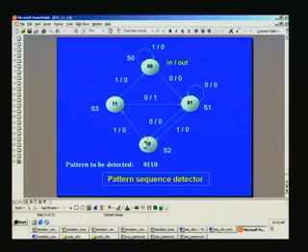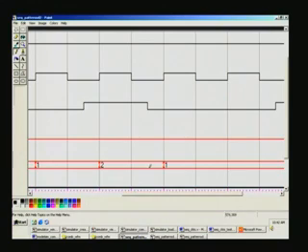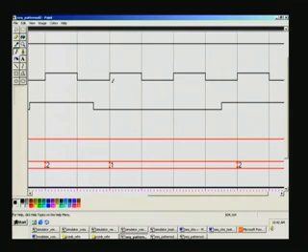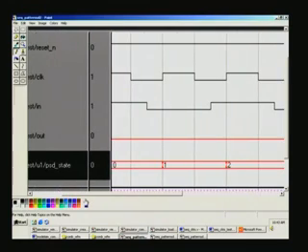In state 2, if input is 1, is it 1? It is 0. 0, okay. If it is 0, then it should go to S1 state. Is it okay? Okay. Right? Input is 0, yes. I think the input is sensed at the positive edge of the clock, yes, as well as the output changes simultaneously, immediately, and not in the following clock pulse. No, the output remains constant 0. We have not encountered 0, 1, 1, 0 at all.